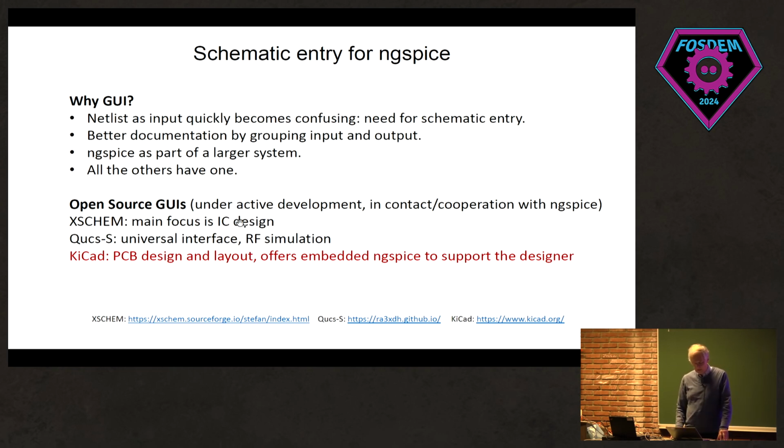This is a thing called XSchem, whose main focus is on IC design. There is another one, QUCS. This is a very universal interface and specializes a little bit in RF simulation. And then, okay, we have the KiCad. So I wouldn't say that KiCad is developed because it's a graphical user interface of NGspice. No, the other way around. Yeah, you have heard about this PCB design and layout tool, and it offers simulation, and the simulation engine is NGspice to support the circuit designer. And of course, I can then make use of this beautiful interface.